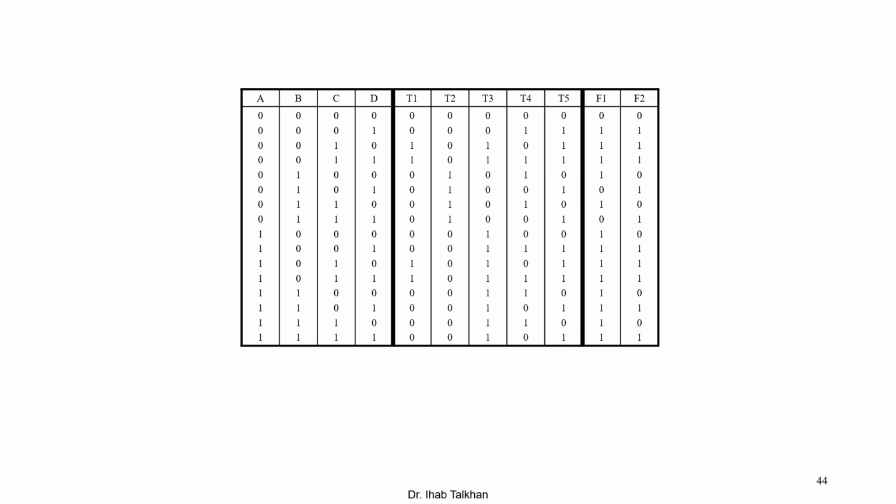As you can see, it's a headache, and there are a lot of errors you can make while doing that. So actually this procedure applies for some applications and does not apply for this example, because this last example is much better done by equation. As long as you have the equation, you can easily find the K-map, and if you have the K-map, you then have the truth table, but it takes less time doing it by equation rather than by using the truth tables.